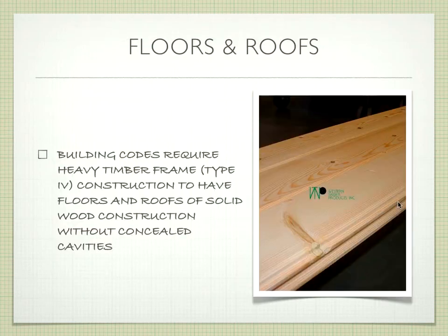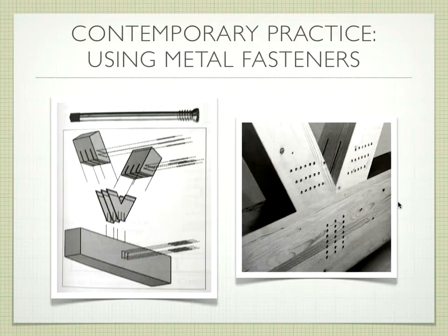Can you go back to that a little bit? Yeah. Is there another piece of wood on top of that? Up here? I'm guessing not. This should be just a glulam, like this. This slides down inside, and these slide over the top. It's possible that they put a trim board on top, but I'm guessing not, because this looks like it ends right here. It doesn't continue. So this should be the top of the beam.